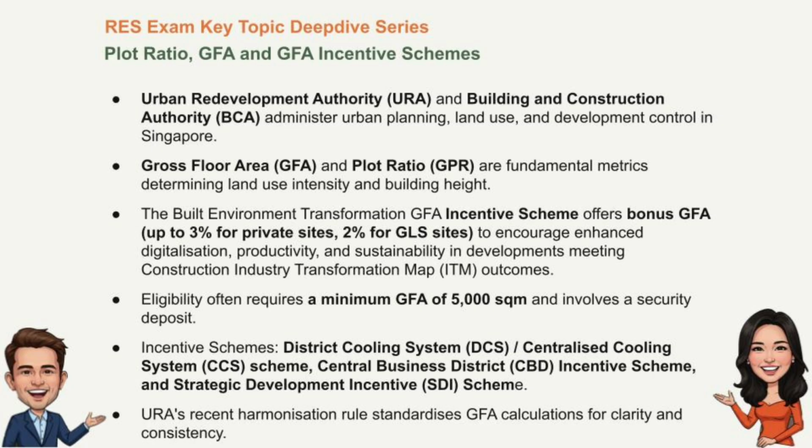And does BCA just take their word for it then? Not at all. There's ongoing monitoring. Developers have to submit progress reports every 6 months during construction. And then there are final deliverables needed at the TOP, temporary occupation permit stage, and even 1 year after TOP. This includes final verification of the Green Mark SLE, IDD implementation reports, productivity data, QM assessments, etc. They really track it. And I heard there's a financial guarantee involved too, a security deposit.